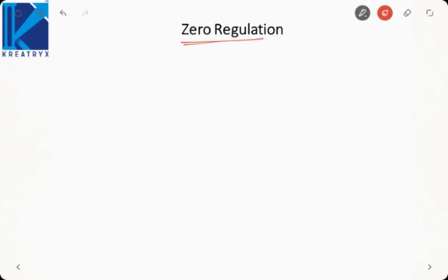So voltage regulation for leading power factor was epsilon R cos phi minus epsilon X sin phi. In lagging load, there is a plus sign between the two. In leading load, there is a minus sign between the two terms. Now, lagging load can never have a zero voltage regulation because both the terms are in addition. So it can never go to 0. So, for making the voltage regulation 0, we need a leading power factor load.